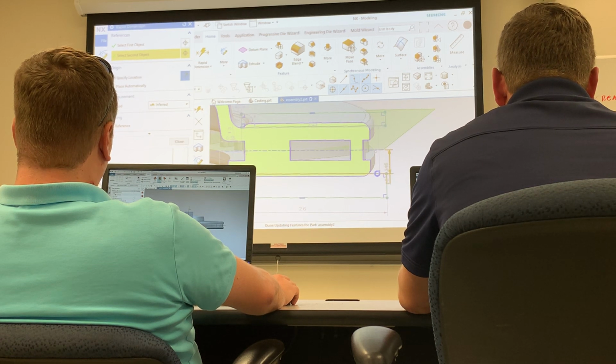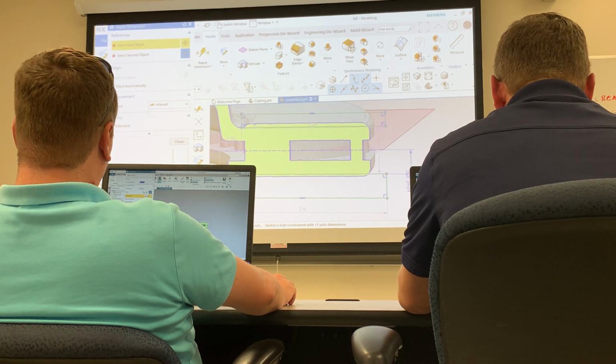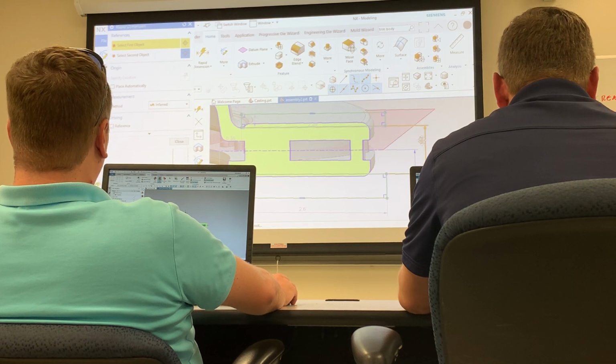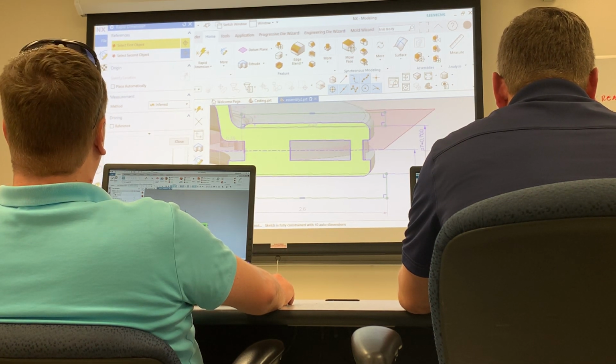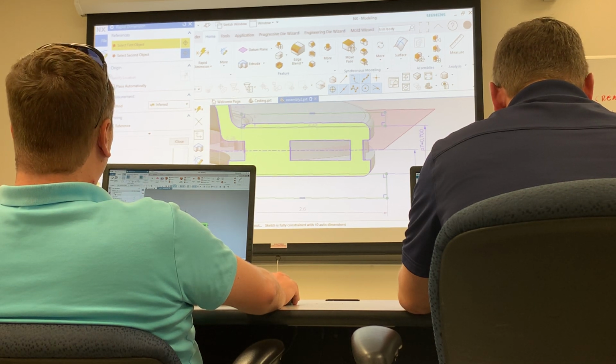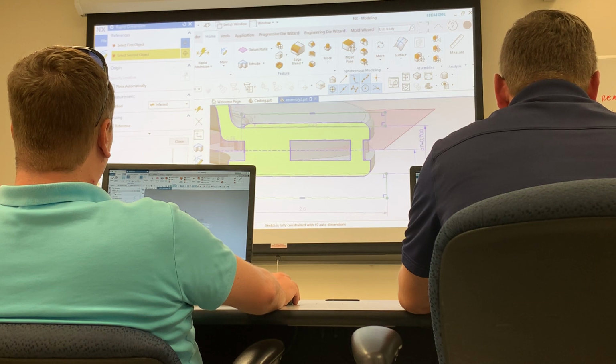So from there to there, that's our 0.35. And this, since it's already an auto dimension there, I can edit that. Now since it already says 0.7, I need to change that text somehow so he knows that it's actually changed. So I'll just make it 0.70. That's good. And the other number is 1 1/4.